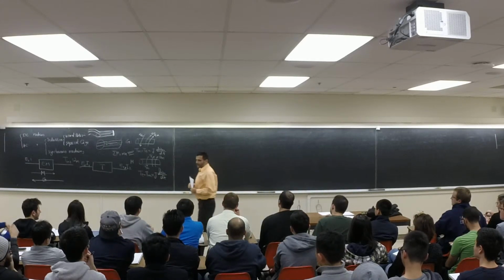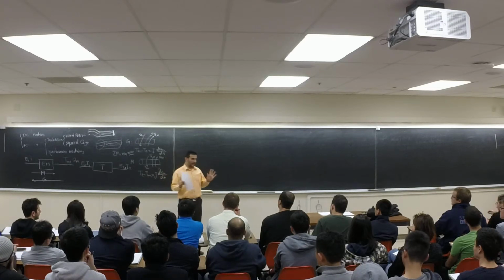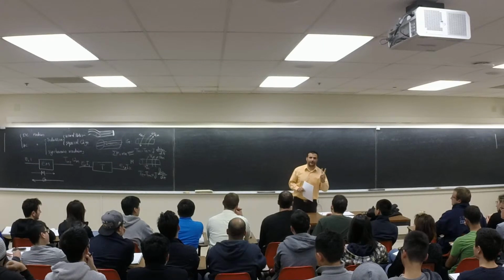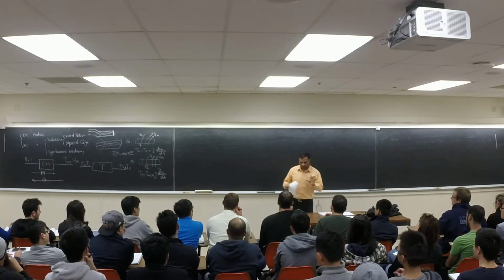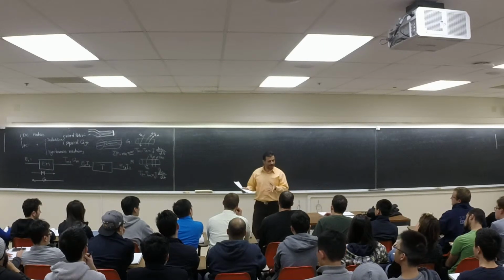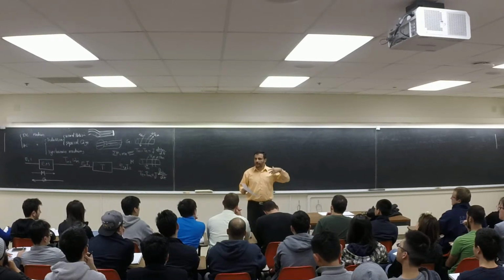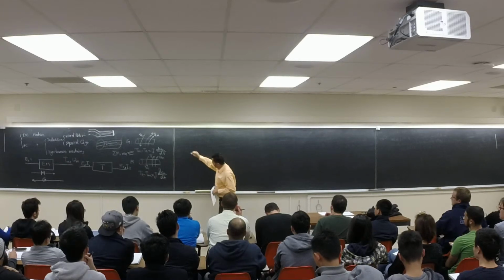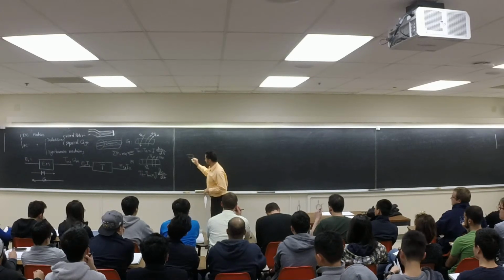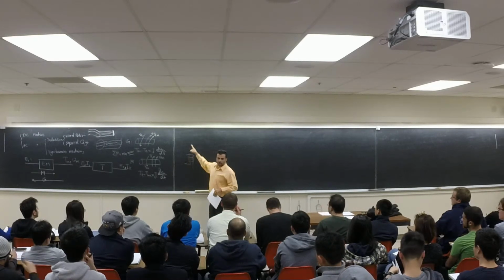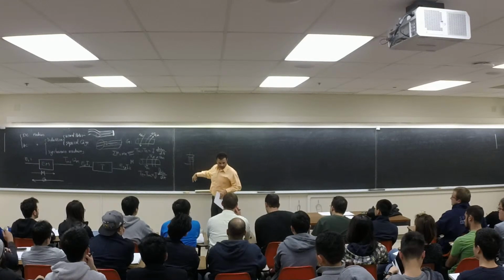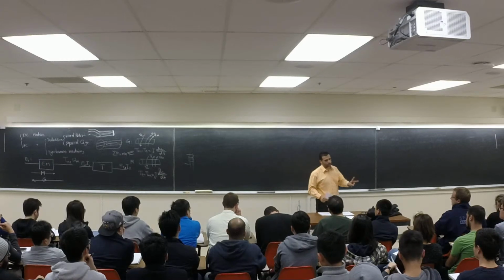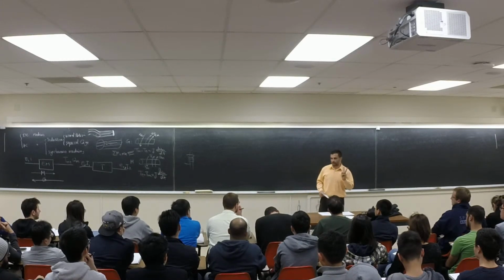If you look at every generator and every motor, there should be two magnetic fields. It could be natural permanent magnets, or it could be an electrical magnet. For example, you have a core and you put a winding on it. As soon as you pass current through it, it becomes a magnet and generates a magnetic field. So you have to have two magnets in every electric machine.